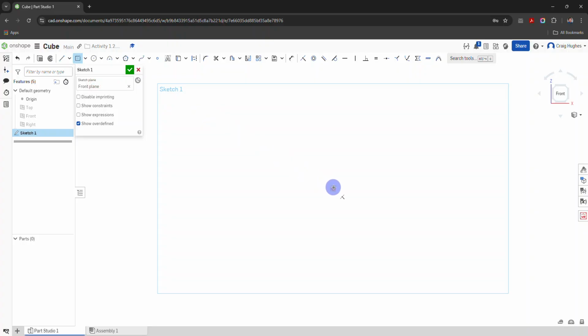the origin as the center, and you'll notice, see that little icon that popped up? It looks just like the one I told you to keep an eye on from before. That's the coincident constraint, meaning that we're going to lock onto that origin when I select it. And you can see that when you hover over it, it turns yellow or orangish. So my little hot cursor highlight might be making that look a little funny, but on your screen that's what you'll see.